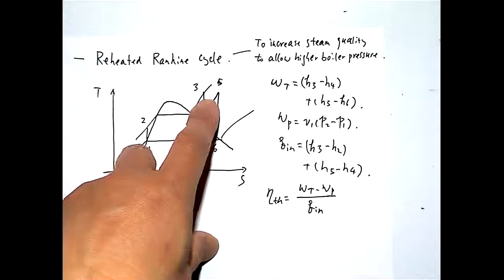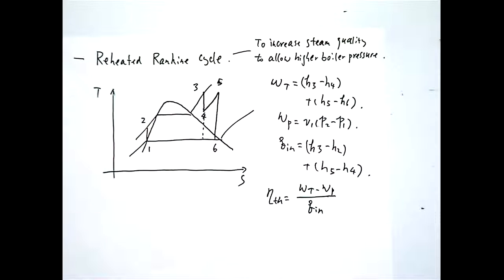So here the purpose is mainly to improve the steam quality. So to push this horizontal line to the right, so that you end up with a higher quality of steam. But in the turbojet, the afterburner is to give you additional thrust. You're adding more energy right before the nozzle so that you can produce higher thrust for the emergency takeoff condition. And what's the purpose of reheater in the Brayton cycle?